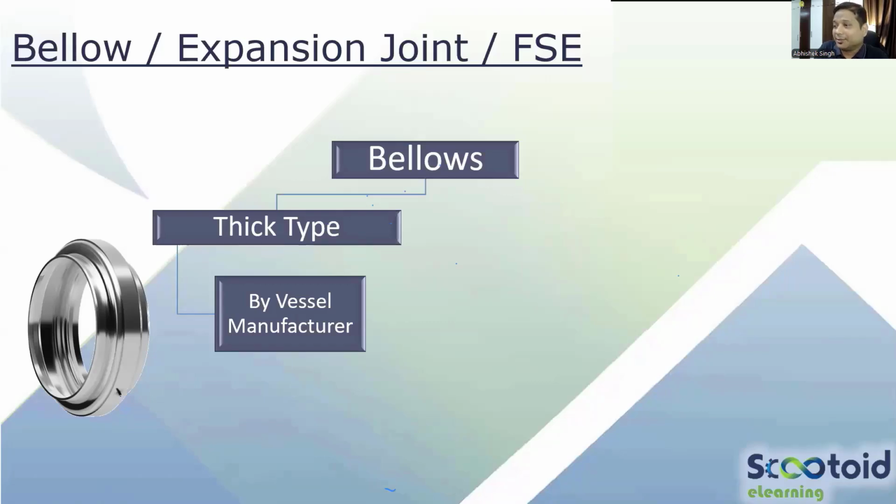Okay. So with the design by rule which is existing, you will be sizing that bellow, and then doing FEA is mandatory. You have to do FEA to qualify. Otherwise, your report cannot be accepted. Making sense? So it's not like earlier when we used to just design by rule. We used to do that for thick bellows. You have to do FEA now. Okay, it's a mandatory requirement.